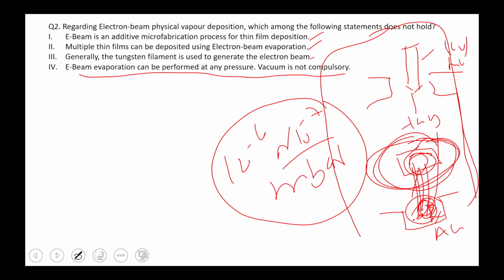Because if the crucible rotated, the electron gun would not stay in one place; the gun electron would be going here and there. But in the video they said they do some XY patterning. How does it affect it? Not X-ray, XY sweeping. They change the position of the gun, they tune the filament in the X and Y direction. Some rotate the filament. The crucible is held in a fixed place.